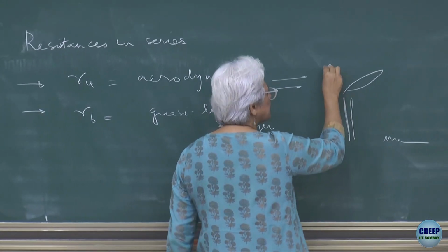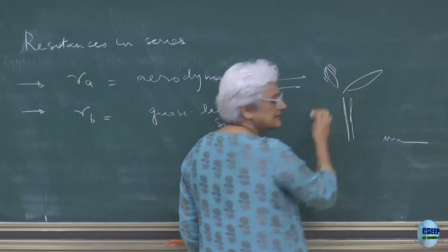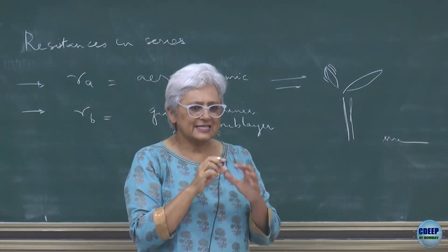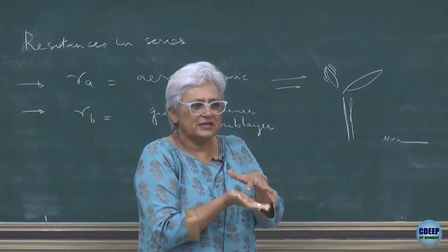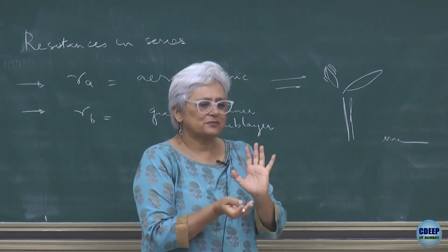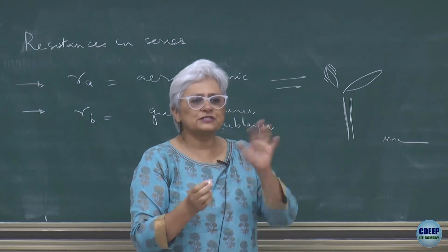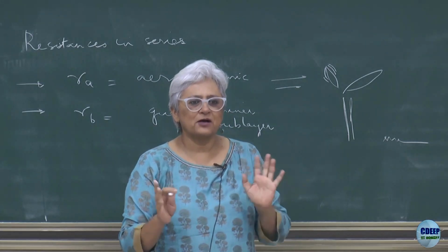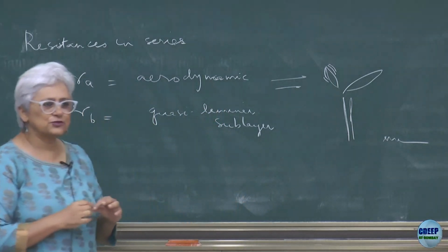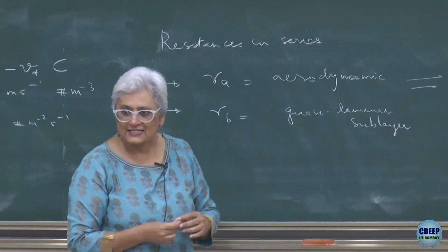The general idea is that there is some part of the fluid that is somehow stagnant close to the surface, and it is that thin layer through which the particle has to somehow transmit itself, whether by diffusion, or by interception, or by impaction, as the case may be.